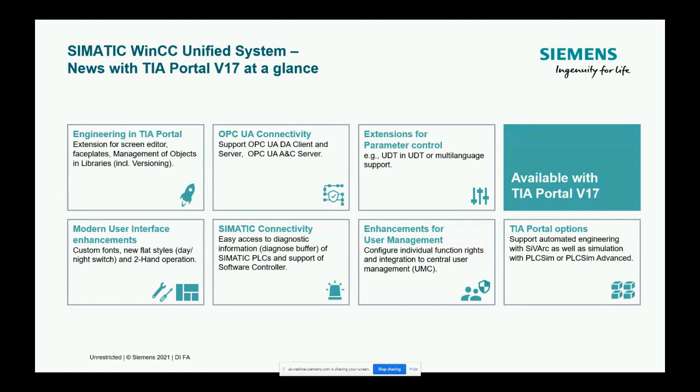And we've included a standard diagnostic control that you can easily integrate the diagnostics buffer of the 1500 directly into the TIA Portal WinCC Unified visualization system. On the user management, we now include central user management for both the panels and for the PC-based system. So again, very, very important and supports our concept around security.